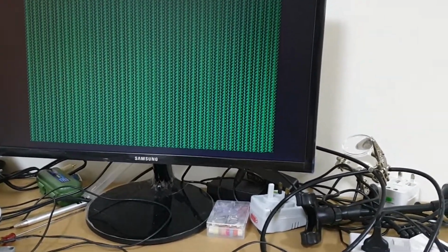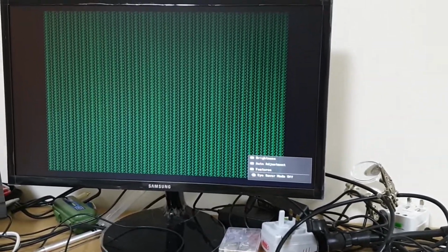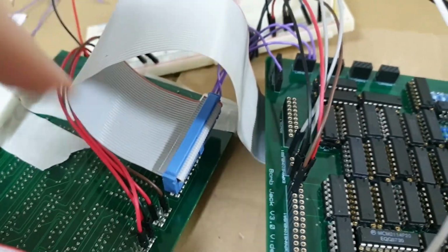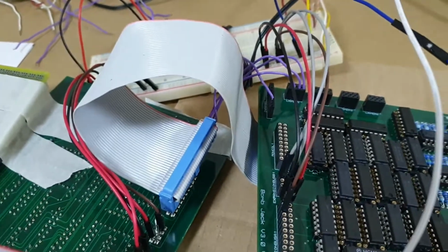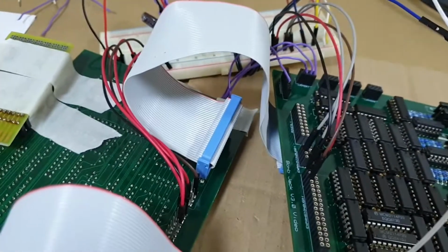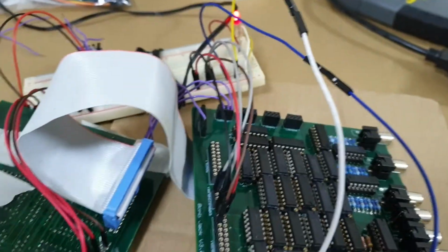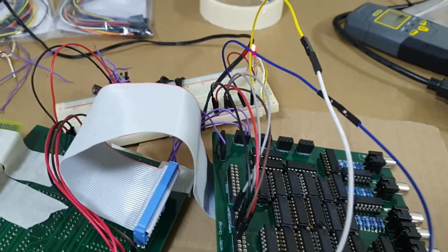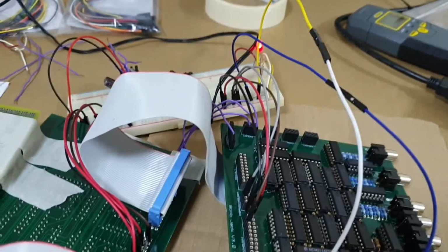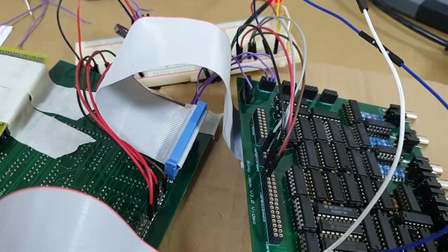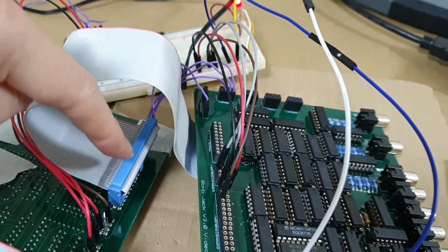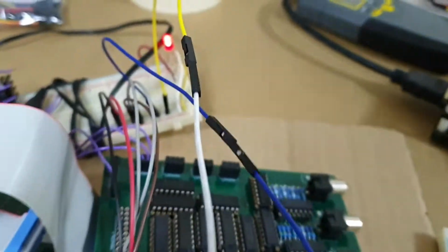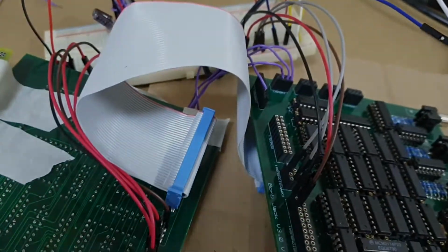So it might be something towards the top end of the header. It might be more than one wire. It might be the fact that it's a very long cable, and we're getting some unintended effects. I'm not entirely sure how to debug this cable further, apart from getting the multimeter out and testing individual connectivity for all of the wires and to make sure that there's no shorts. But it looks like there may be an issue somewhere near the middle of the plug on a range of pins. Bother, more debugging needed.